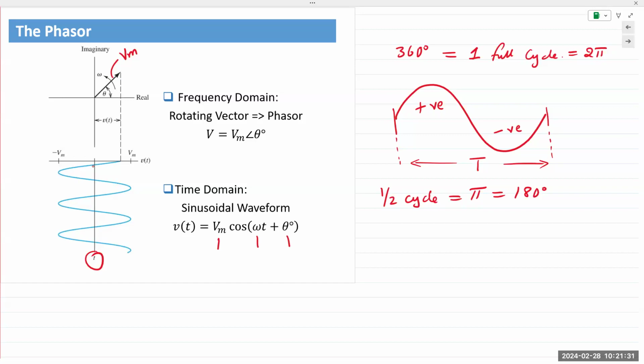Even though we typically use peak values, the book that I use uses m because we describe the time domain expression as a rotating vector with the length equal to the magnitude, Vm. As a reminder, Vm is again the peak value, Vp. If you take a different class or read a different book, this expression might be written as V of t equals Vp cos omega t plus or minus theta. Exactly the same thing.